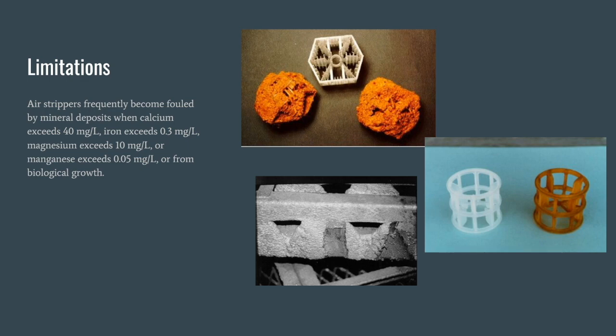Low-profile air strippers are often desirable when fouling is happening. Low-profile units are often fastened together, tray by tray. Small units can easily be disassembled to physically remove the biological or mineral deposit. Larger units have access ports on the side of each tray for cleaning with a high-pressure water spray.